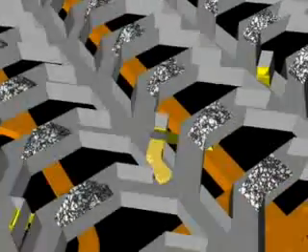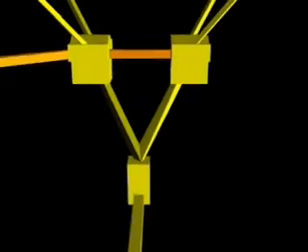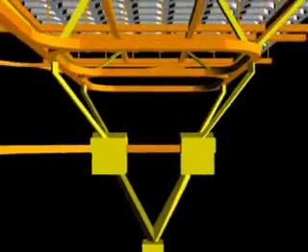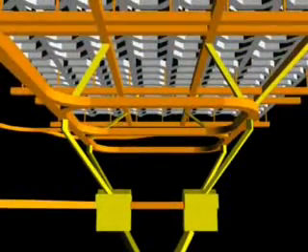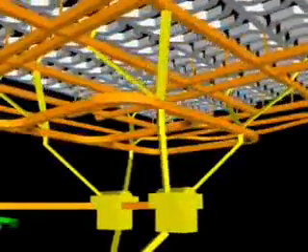The ore travels down the ore passes through the influence of gravity and passes into the underground crusher stations. The crusher stations usually consist of large jaw crushers that reduce the average size of the material to that which can be more easily handled by the haulage and transport equipment. The ore may also be screened through a series of parallel bars called a grizzly. The grizzly prevents oversized material from passing and causing damage further in the ore transport process.